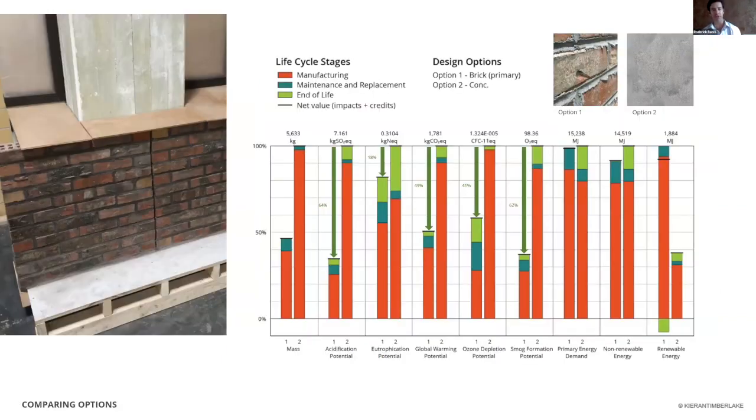So maybe you've done those big decisions and now you're getting a little bit more into nuanced design and you want to compare some actual options. In this case, the functional unit that we're looking at is a lower portion of a wall on a building, one that's brick and one that's concrete. And how do these two compare against each other, say looking over 100 square feet or something like that of this particular assembly? And you can see when we look at these the dramatic difference in impact. And it really sets up a very effective comparison. And obviously there's a lot of other factors at play, but this is one in which you say, okay, if you're trying to prioritize global warming reduction, clearly we want to look at the brick option in this case.